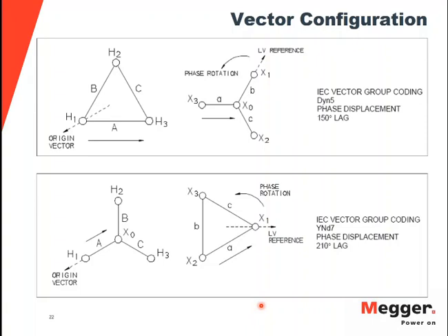Okay. Well, let's go back to the physics, right? When you are running a winding resistance test, basically you are giving an orientation to the magnetic domains of your transformer. By doing this, you're saturating the core. And when you have the core saturated, if you energize your transformer, what's going to happen is that you will have high inrush current. And you will generate especially odd harmonics here, especially you will have a big component of second harmonic that may trip your protection system.